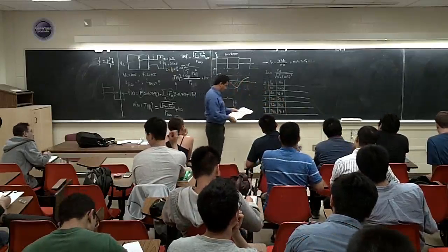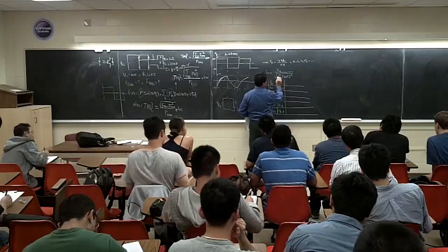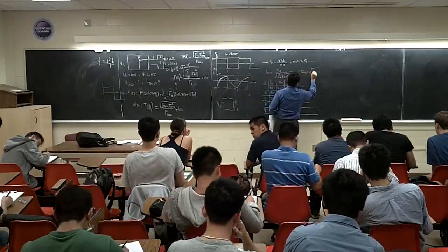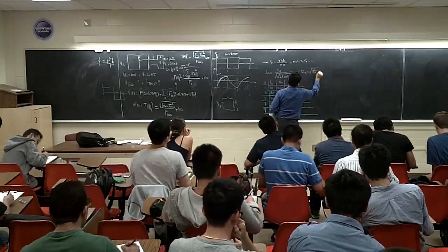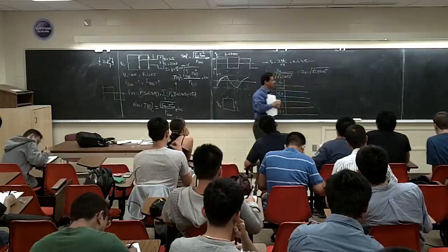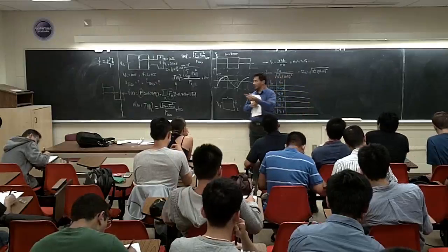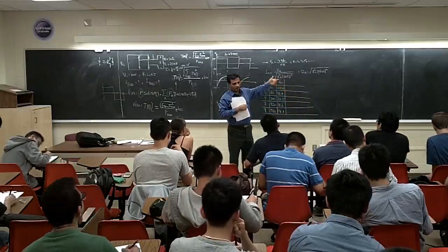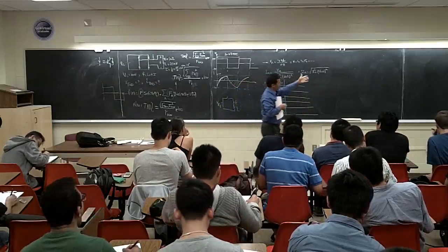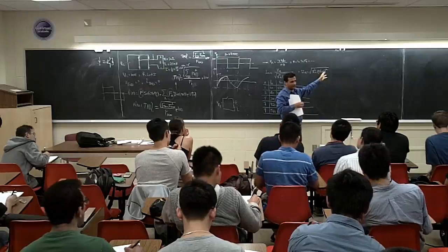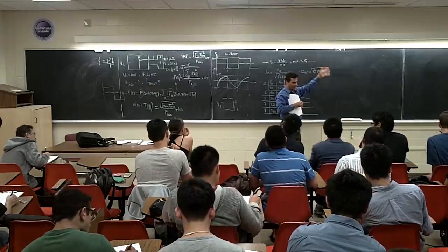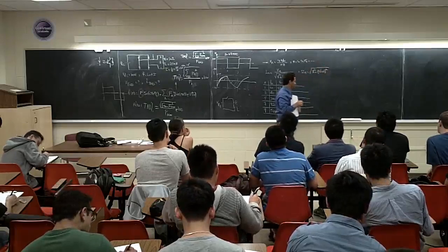Now the next one we're going to calculate is Zn. You can call this one Zn. Zn is going to be the square root of R squared plus (nLω) squared. So Z1, how much is R? R is 10 ohm, L is 25 millihenry, omega is going to be based on this frequency. So omega you can say is 2 pi f, 377, but for the first harmonic it is 1, for the third it is 3 times that, 5 times that, you calculate those.